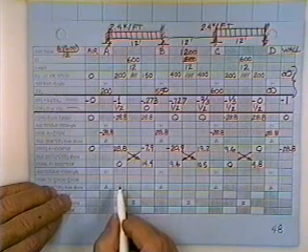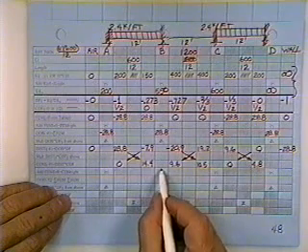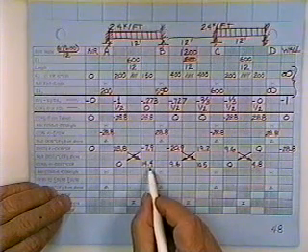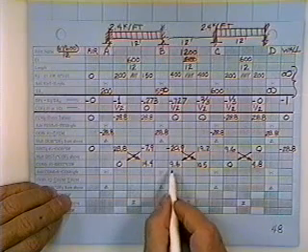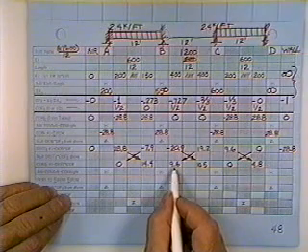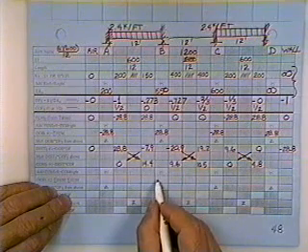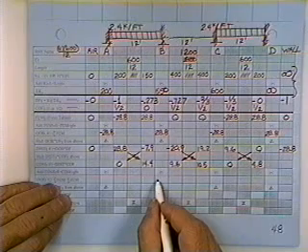Next, I have some really bad news for you. At joint B, 14.4 slid over when guy A let go of his wrench, and 9.6 slid over from joint C when that guy let go of his wrench, and the two add together, causing some more imbalance in joint B. So the guy at joint B didn't get to go home after all.